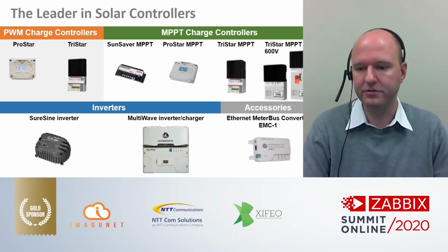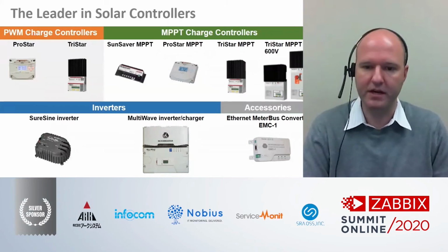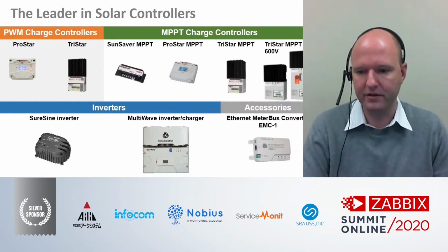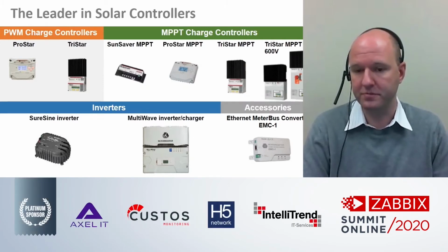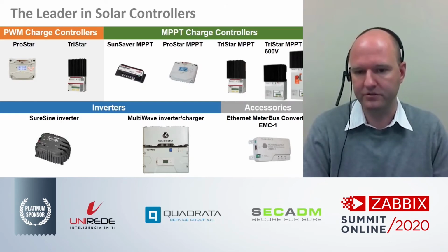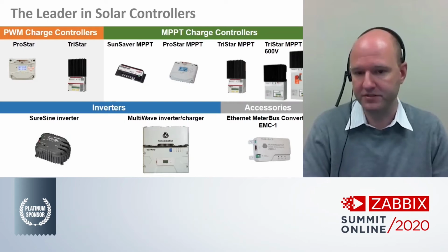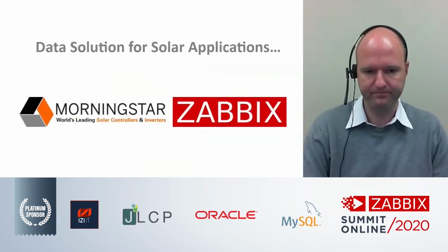It's a simple serial to Ethernet converter that also supports a real-time operating system and a variety of protocols so that our products can be connected to industry-specific applications using those standard protocols. And these would be MODBUS over IP or SNMP, and it can also display a simple HTML web GUI to allow direct connection on a one-to-one basis with the product for simple status monitoring using any type of device, including mobile devices such as phones or tablets.